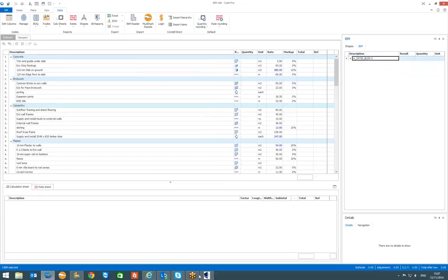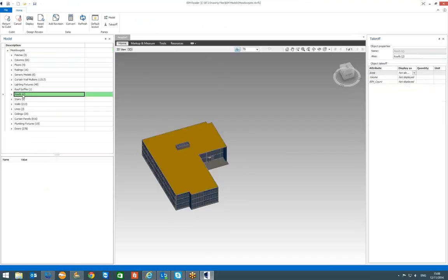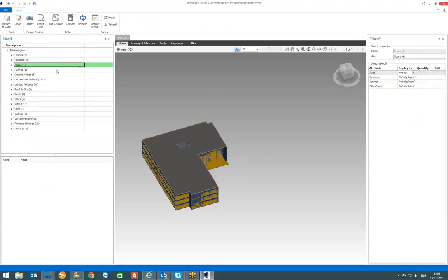If you're returning multiple, if I went into the other one, and let's say, for example, in this one we wanted to know what the roof areas were. So we highlight roofs, and we can just say, give me the area. So you can pick off what you need, same way with columns, whatever it be, you just highlight it, pick the result type.